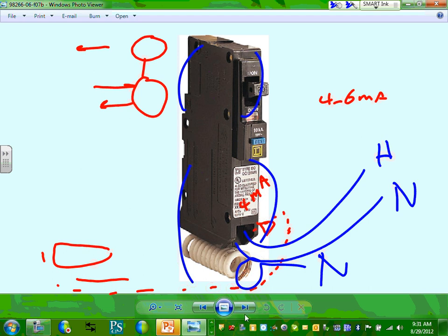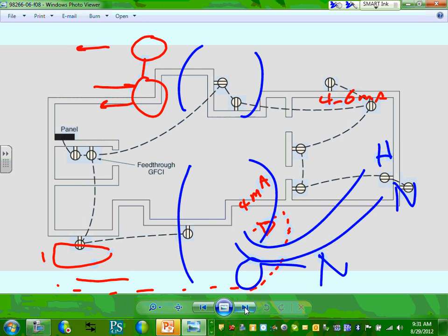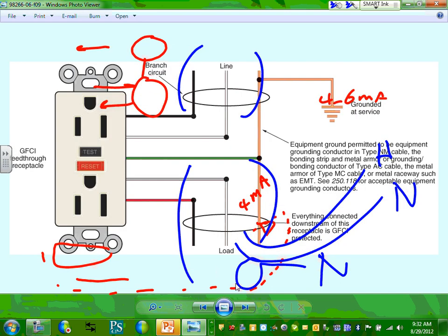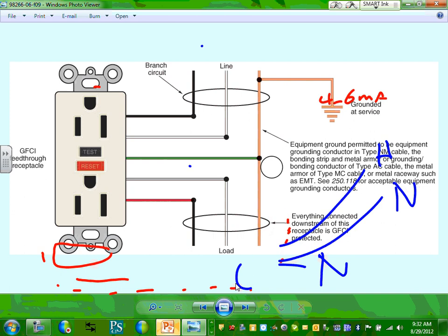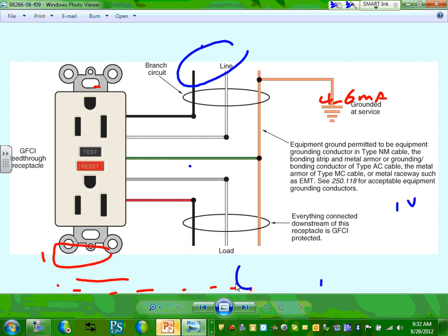Same thing for ARC. GFCI. Here's what GFCI is, guys. I can't emphasize enough when you do the wiring, of course, you have to have GFCI in and out. If you don't do it in this format, it won't work, right? So can I have a thumbs up, Chad? We know what the line side and the load side are here. Cool. If you mix the line, if you take the neutral from here, you're screwed up. It has to be hot neutral in, hot neutral out, in that order. If you bring the hot to the load and take it out to the line, that also would trip.